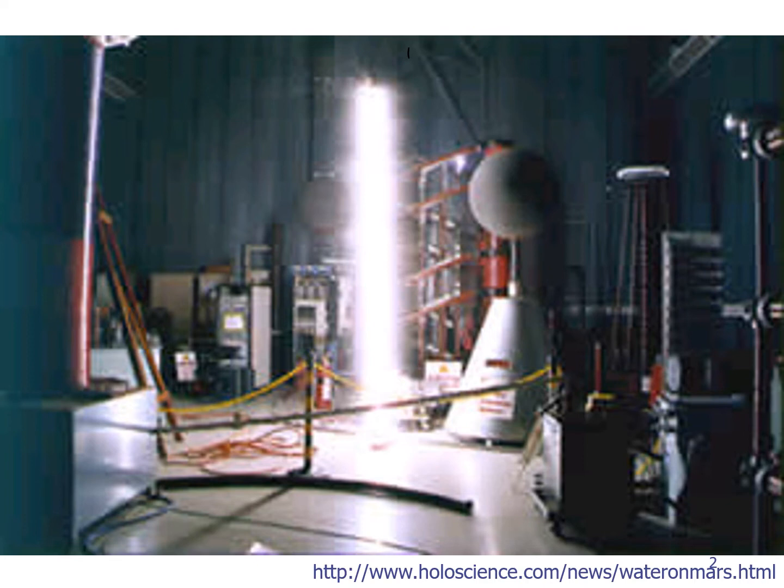Those wires create what's called a corona discharge, and this is a picture of what it would look like. It causes an avalanche of ions. There's a very strong voltage on it, and it breaks apart some of the air molecules nearby and causes them to release electrons and ions, which then attach to the particles. We'll talk about that in more detail.